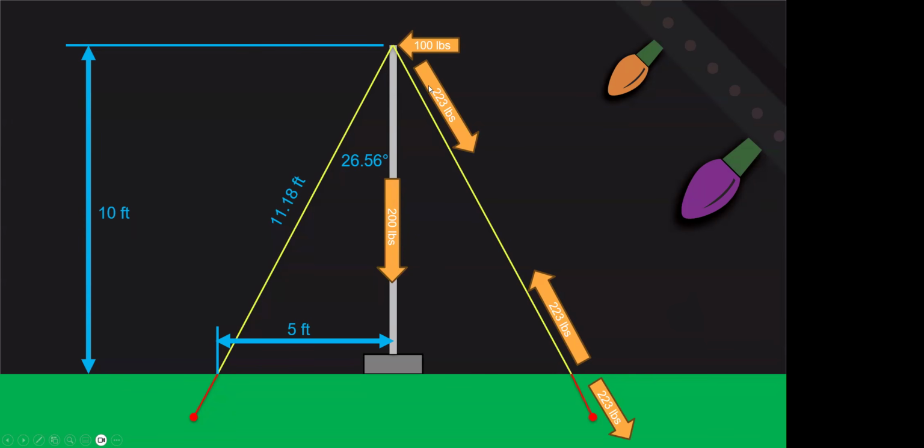Something to pay attention to with this, and I know a couple of the guys in the Zoom room have been talking to people about it: when you're tensioning up your guy wires, you don't want to over tension them and put a lot of force on them, because any force you put through this guy wire is going into your pole as well and could potentially buckle your pole, like I showed in one of the first slides with that little arch shape. The good news is if you have the guy wires at the top, these poles are relatively stable.